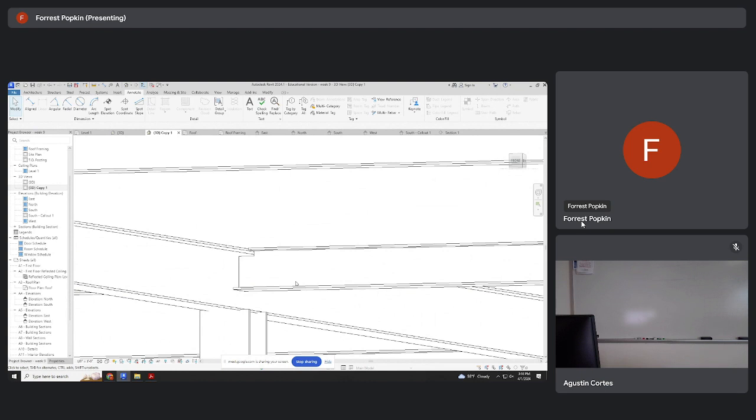Professor, just to confirm, about the decking, so you add the decking and then go into the detailing to offset it so that it doesn't interfere with. Well, that's not the detailing. That will actually move it in the model. Okay. Yeah, so when you're manipulating the levels and stuff, that's legit. But I guess my point was, in this instance, I was kind of working backwards. So what would conventionally happen is that you set your floor to whatever you set the floor, right? And the reason for that is because that number is set by a bunch of other parameters.